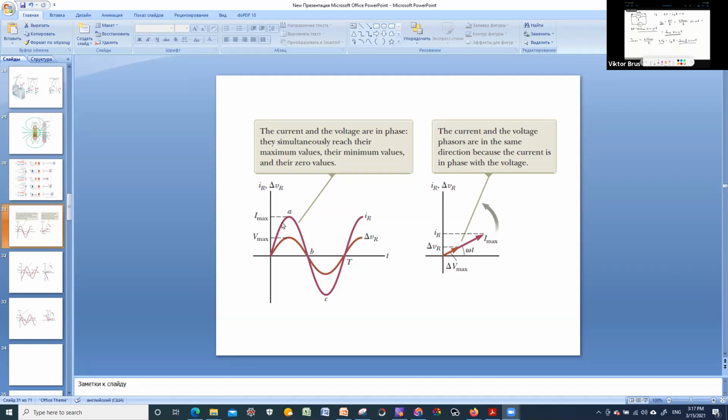However, we see that current depends on time, and that means that power which is delivered to the resistor also will not be constant. That's why it's useful to find some value of electric current, like some magnitude of DC electric current, which will result in the same amount of energy delivered to the resistor as it would be with some alternating current which changes over time sinusoidally.